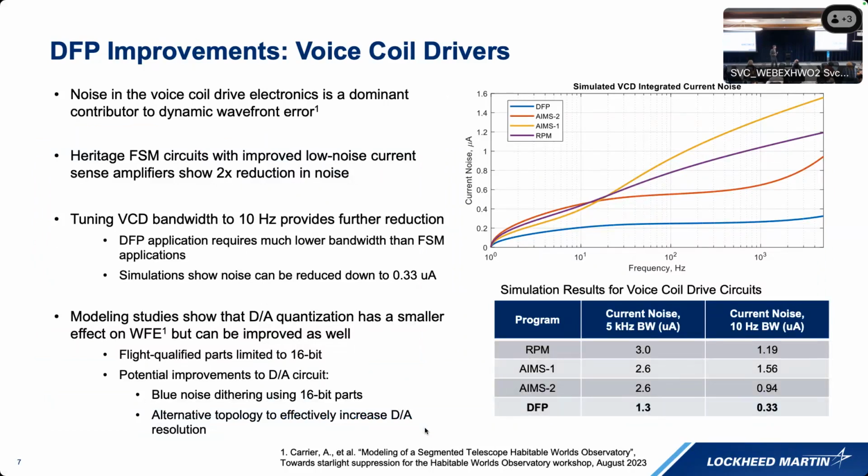We're working on this under the current TechNest funding. Here we're looking at reducing the noise from the voice coil drives. As I mentioned, these voice coil drives are based off of heritage flight fast steering mirror hardware. But we've been tuning and adapting them to the DFP application, to the HWO application, that allows us to reduce the current noise significantly, and that has a significant improvement on the total wavefront error.